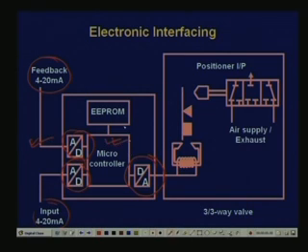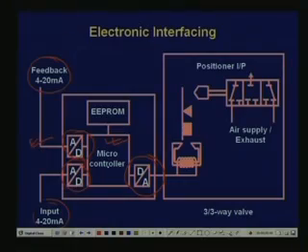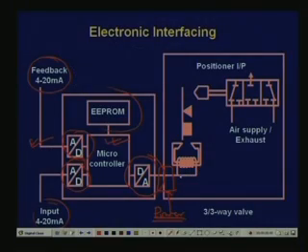We have just shown this to indicate that it is also possible to use a digital controller, let us say a microprocessor, to control these. This is the microprocessor CPU and this is the memory. The microprocessor finally gives a digital command which is converted to an analog command. In general, there will be a power amplifier, because a microprocessor generally cannot drive a coil. Typically one can use relays, or one can use power amplifiers. So finally a current is driven.